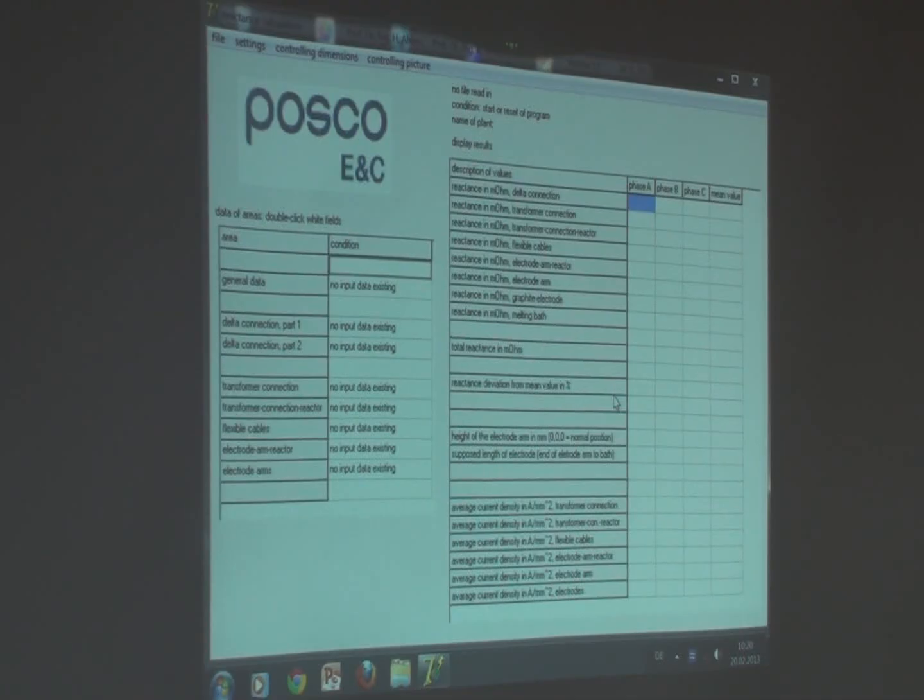This is sine 2 phi. And this 3 you can forget, and therefore we see P is the square of the phase-to-phase voltage divided by 2x multiplied with sine 2 phi. This is the formula.